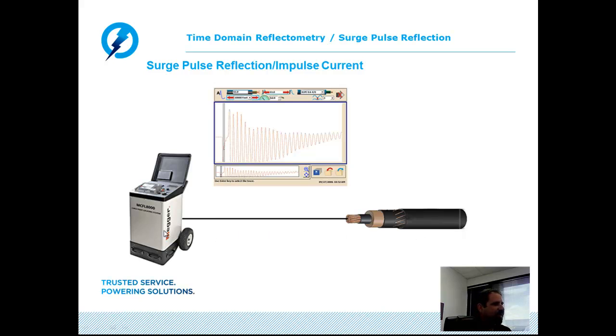Now, upon reaching the test equipment, that transient reaches the capacitor of the thumper, reflects again back toward the arc, and this continues to occur, where this transient oscillates, or rings, if you will, back and forth between the arc and the thumper capacitor until all of the energy has been utilized or dissipated.